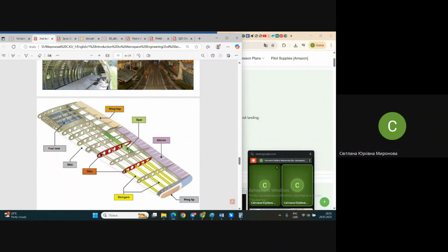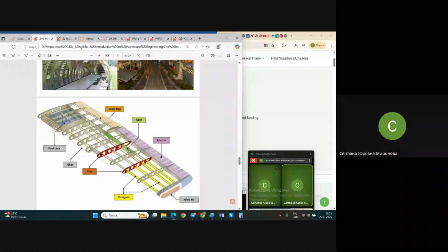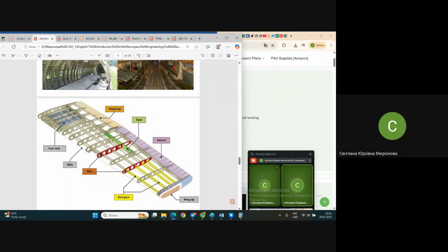But instead of stringers, let's say, middle loaded aircraft usually have spars and stringers. The aircraft which fly with low speed, it's very similar to the explanation about fuselages. Low speed aircraft usually have a wing structure which consists of spars and transversal elements, even without stringers.